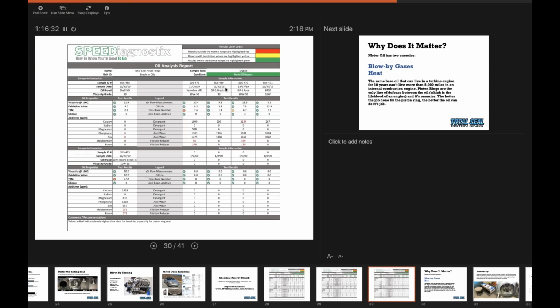For your just street high performance guy, a really easy upgrade if you're using shelf pistons that are not gas ported. A lot of those shelf pistons are going to be either a 5/64 or a 1/16 ring groove design. We have ductile moly cast rings that are gas ported. They're on the shelf. Because of the size of that ring, there's so much material there.